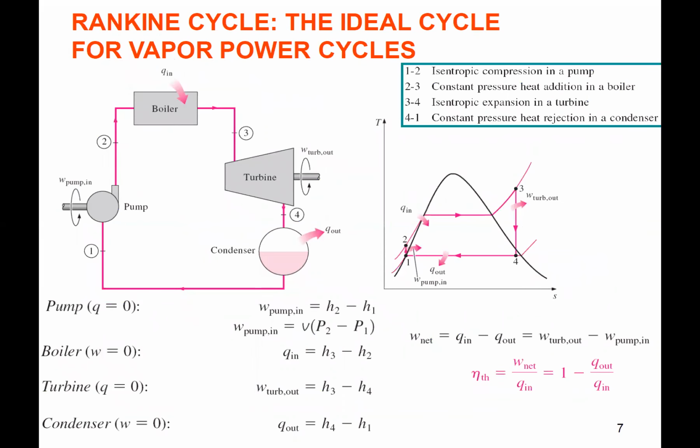All right, so this switches to chapter 10. So now we still have open system, but we're using that phase change. So now we're utilizing the phase change, and the components are an open system, right? So it's still kind of doing the same thing that the Brayton cycle did with an ideal gas, but we're changing it because we have the vapor dome now, because we're utilizing phase change. So we have a pump from 1 to 2 where we raise pressure because we're in the liquid region right here.